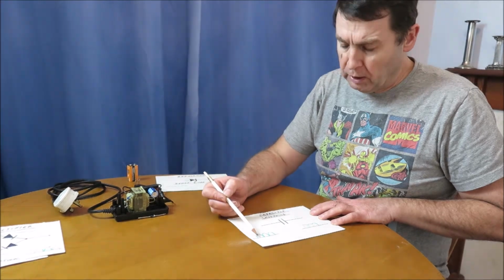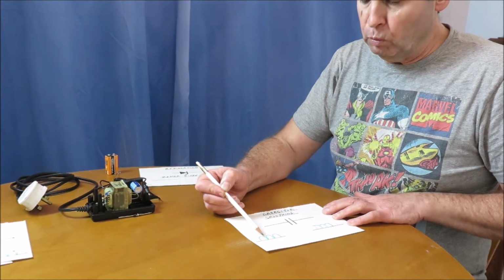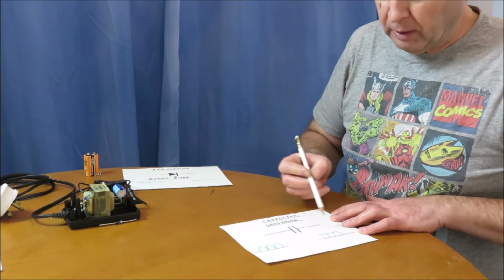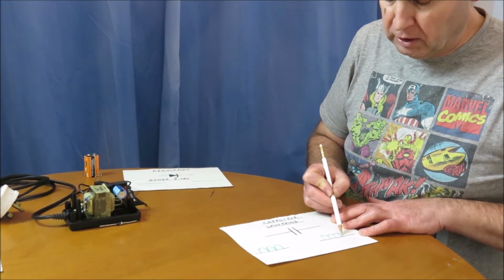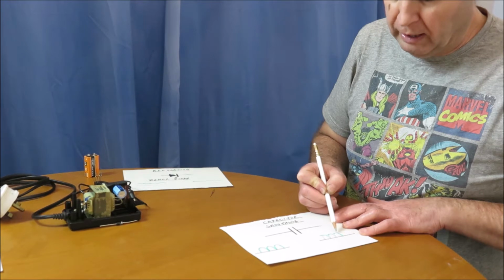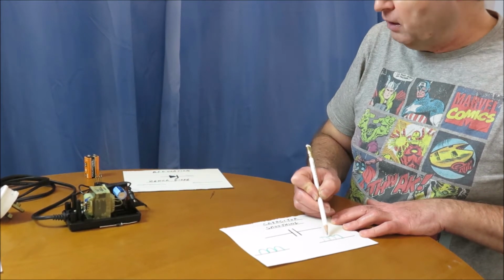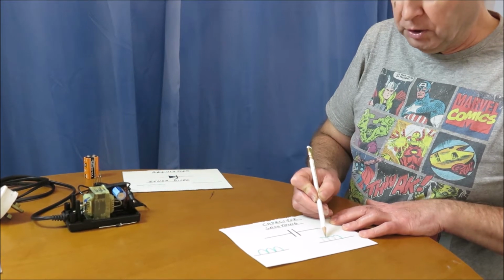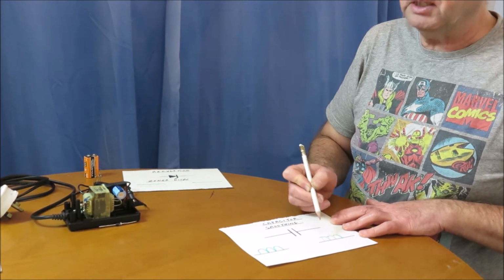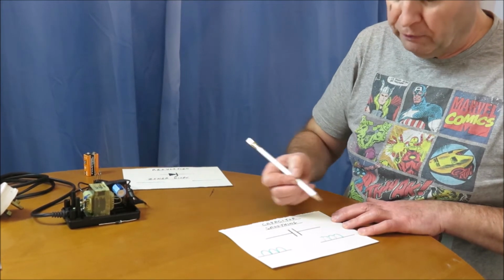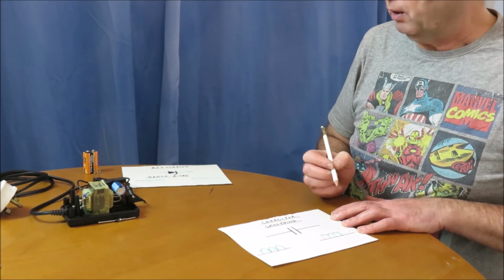So what we do is we put the full wave rectified supply across the capacitor, and the effect of that is it smooths it, so you will have just a small ripple voltage. So it's getting towards a line there, but as you can see there is some ripple in it. Now that depends on the size of the capacitor as well, because with a big enough capacitor you can take most of our ripple out.